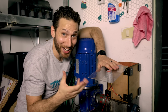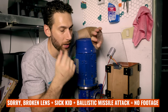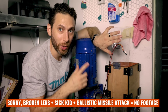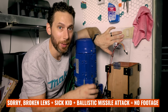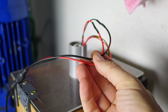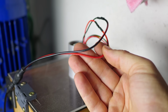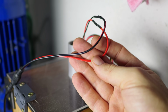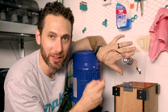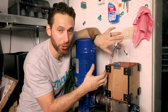As for whether or not this actually solved my problem, the jury is still out. It definitely pushes a ton of heat through the shredder, and when I run it, particularly if the shredder is going in reverse, I do notice an increased amount of material actually exiting the sieve. The problem here is that the barrel jacks that I had on hand are not nearly a high enough gauge for something that draws as much amperage as this fan. So they are heating up like crazy, and I can't actually leave the fan running constantly. So I am still struggling with both heat and material buildup.